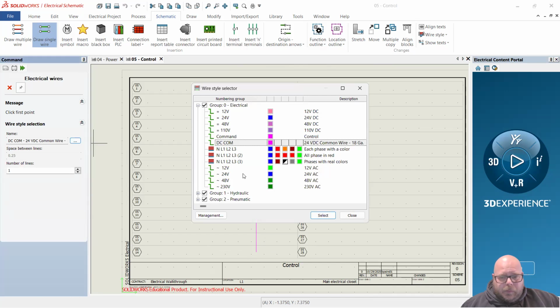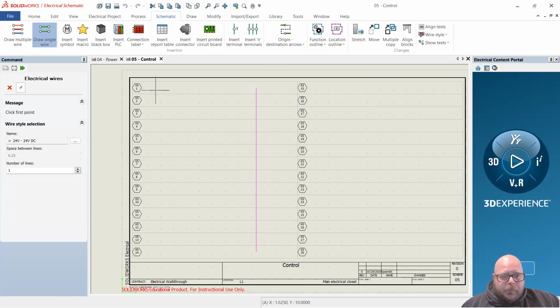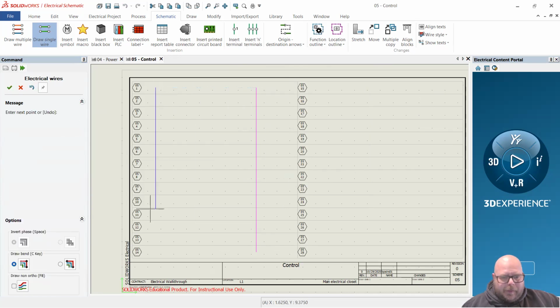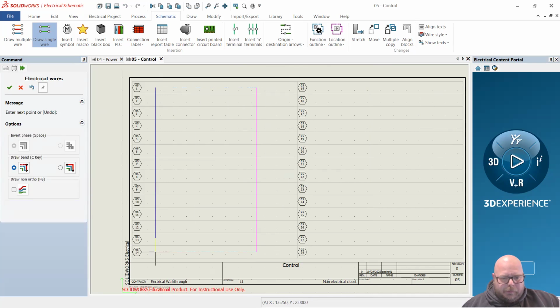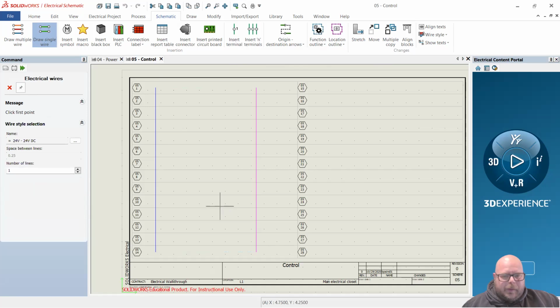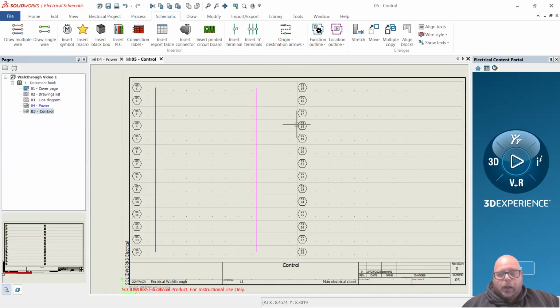The plus, let's grab one. Oh, that was the AC. The DC always goes on the right. And again, I leave a little more gap on the right side because later on there are cross references and text that we need to fit over here. So leave a little gap also on this side between the border and these labels and this rung. Here, I use my cursor as a guess to get the spacing correct, right? I use the plus sign of the cursor off of the hexagon to get that spacing. So now I've got two wires.